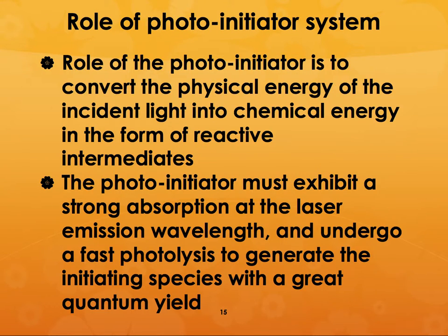So what is the role of the photoinitiator itself? It is to convert the physical energy of the incident light into chemical energy in the form of reactive intermediates. It can exhibit a strong absorption at the right laser emission wavelength and undergo a very fast reaction to generate the initiating species with a large yield so that you can produce the part in a very short time.